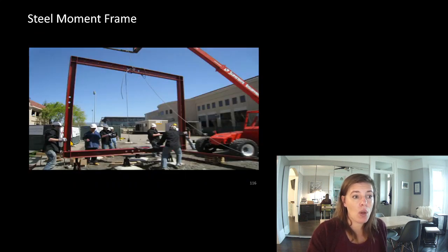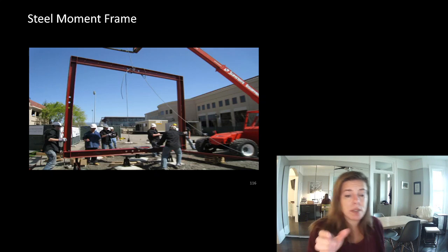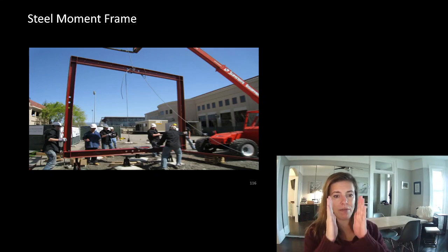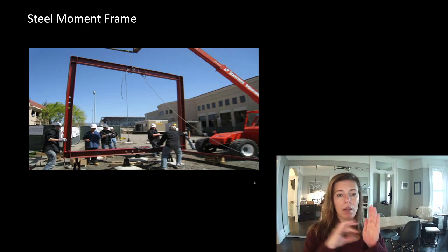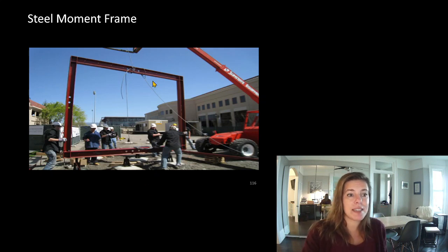Here's just a small steel moment frame. We always talk about the Toronto Special, which is a townhouse. They're usually long and very narrow. And at the back, they always want to bust out the back wall and make it a sunlit kitchen in the back. But now they've taken out their lateral load resisting system, and so we often have to come in and put this steel braced frame in.